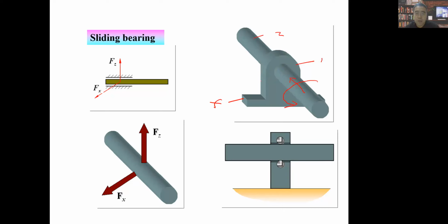So if these two directions of movement are prevented, or constrained, then it will have two directions of reaction force like this and like this. So this is the same thing. If we imagine that we cut it into two parts and just look at its internal, right? This is a reaction force. Actually, this kind is not commonly used in our coplanar force system, right? So you also only need to have an impression here, that is enough.